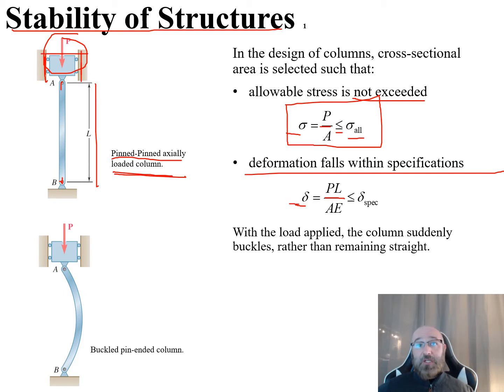So our deformation falls within the specifications here: that load times that length L, all over the area A times our modulus of elasticity E. All of this needs to be less than or equal to our specification, so this falls within the specifications that were given for our deformation.